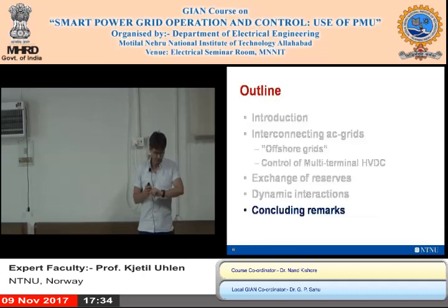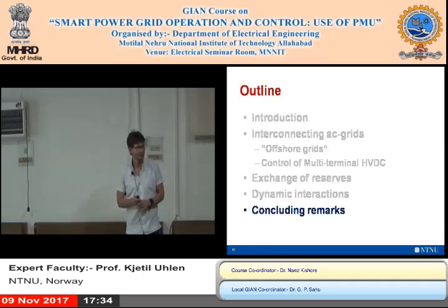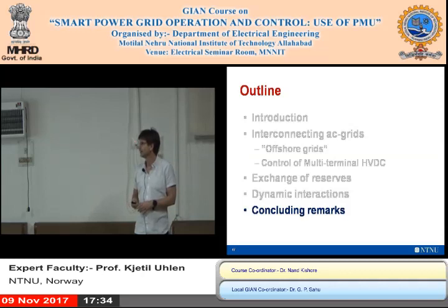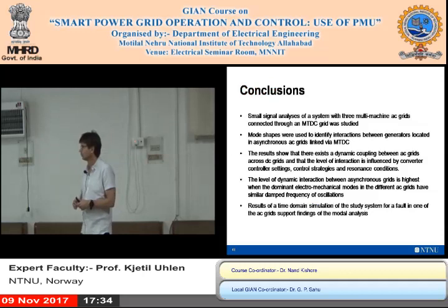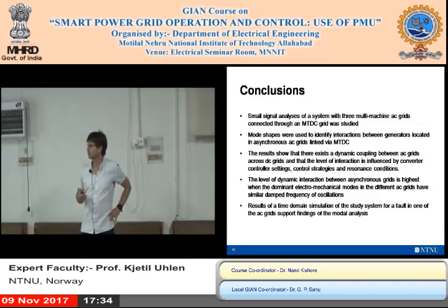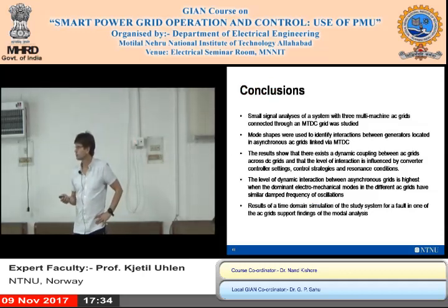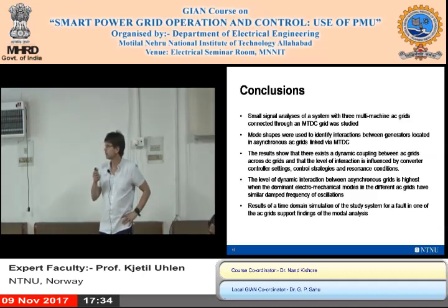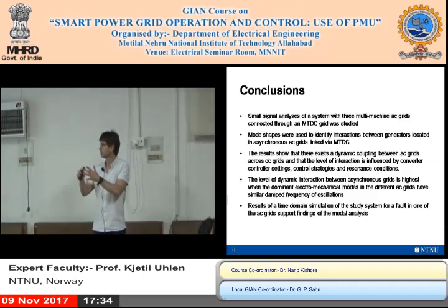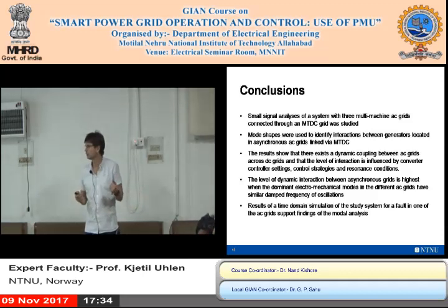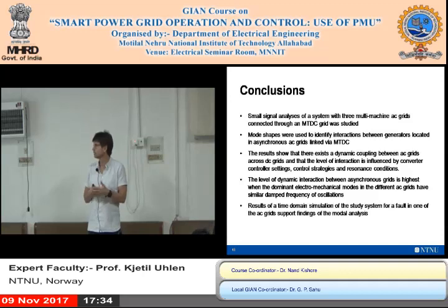So I think it's time to wrap up. Yes, you're getting tired. So what we showed in this lecture was small signal analysis and simulation studies with three separate AC grids connected through a multi-terminal DC grid. And we used mode shape and eigenvalue analysis to analyze interactions.